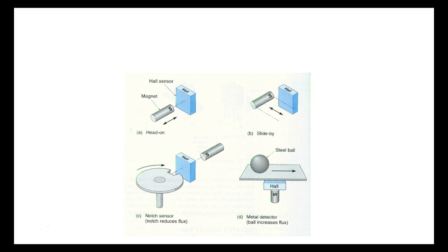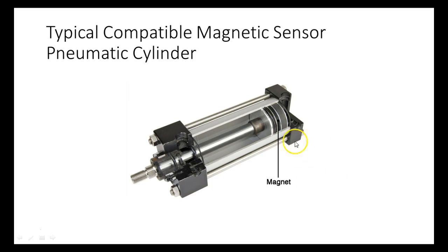So, in our cylinders, we have magnets inside of them. So now we can use either Hall effect or we can use a what? We can use a magnetic reed to sense where that's at. What are they going to use? Well, it's up to the people who get there. You know, fluid power, we've got some switches that simulates a reed switch. It really does.